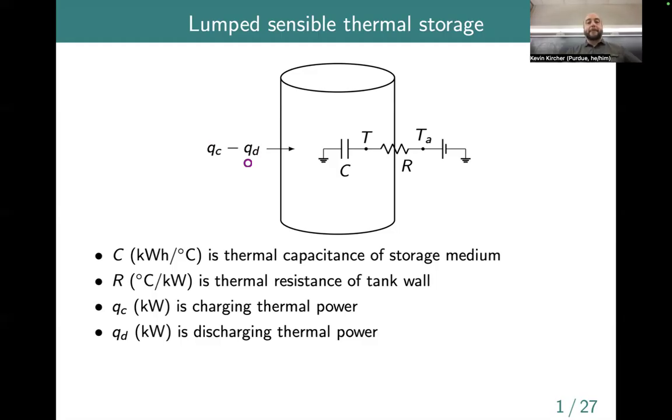Is that battery on the right of the TA supposed to represent the thermal energy coming in? Yeah, so I don't strictly need to draw the battery in these circuits, but the role of this component in the thermal circuit is to maintain the ambient temperature. So you could think of this as, if the tank is sitting in a basement and that basement is heated, the action of the furnace or the heat pump or whatever it is that's keeping the basement warm.